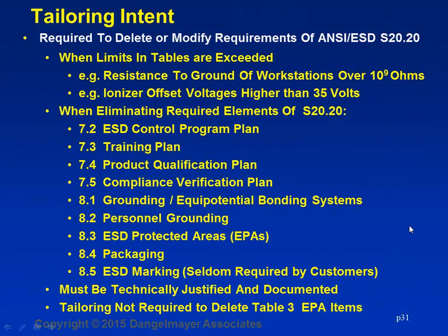As a counterpoint, ESD wax sometimes will measure in the 10 to the 10th range with walking voltages still down below 10 volts. There's another question about how often flooring should be tested. That's a question that varies on the flooring that you've chosen and its long-term stability. For instance, if you use ESD wax, I would test it every week or anytime you see evidence of a spill. Water on wax will compromise its performance. A conductive vinyl floor is much more durable, and testing it monthly or some other interval may be perfectly appropriate. The bottom line is to do it.